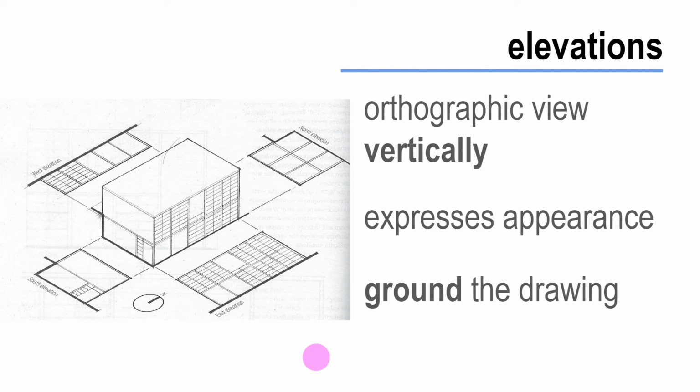So again, it does take a lot of time to practice our orthographics. What we're going to do in class, at least in this current semester, spring 2022, and I say that because I'm hoping to use these videos for multiple semesters, but maybe change up some projects, is I'm going to give each of you a little bathtub toy for you to sketch out, very loosely sketch what it's going to look like from those 6 principal elevations. What does it look like from the top, from the left, right, front, and back? And just to help break it down into those 2D projections. And then as we progress through the course, we're going to see how that relates to different buildings.